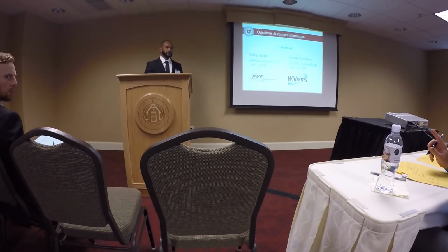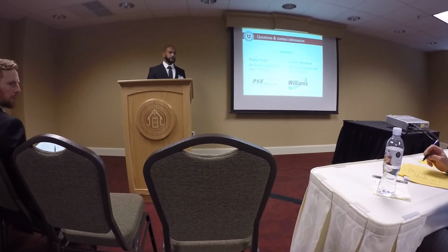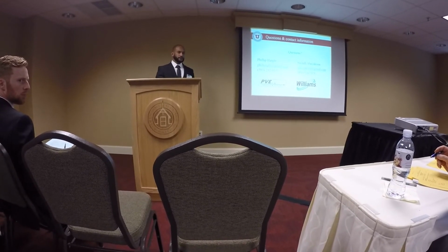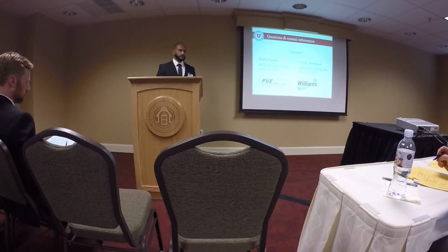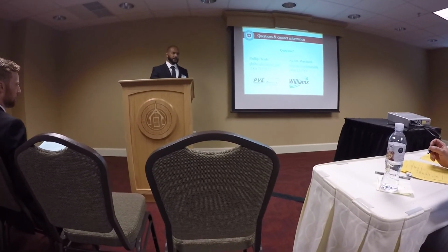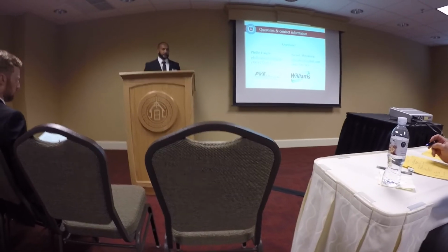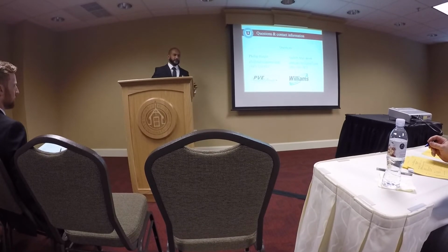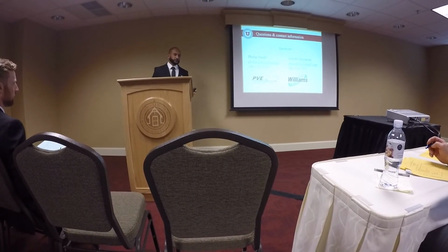You talked about some of your lighting design. Did you have to look at lumens and the actual light intensity on work surfaces, and how did you go about that analysis? Yes. They gave us 800 to 900 lux of illuminance for each room, saying this is the room and this is how bright it should be.